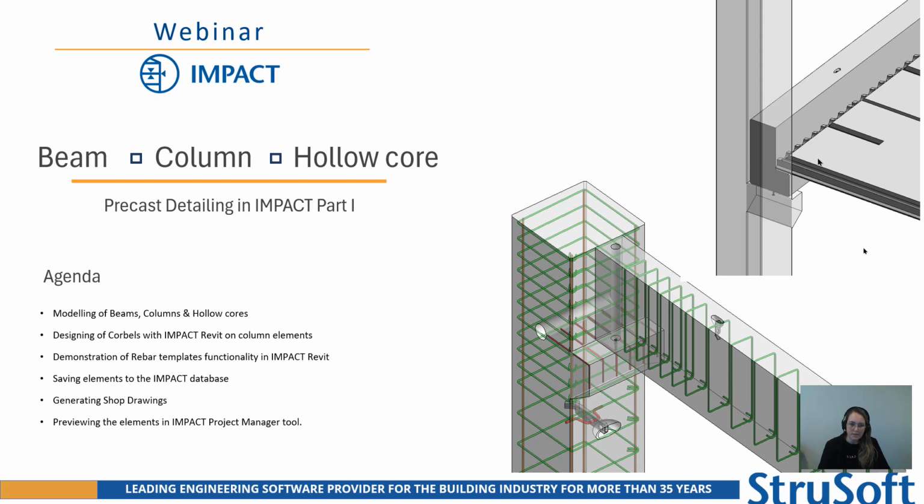Once we're done with the modeling, we're going to save the elements. We're going to generate shop drawings. Again, here we're going to use a shop drawing template. I'm going to show you how, in a few seconds, you can have the front views, the sections, the schedules that you've set up in your template and get some really presentable precast detailing of a shop drawing.